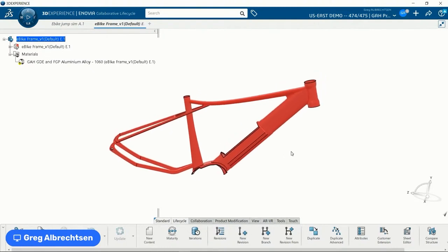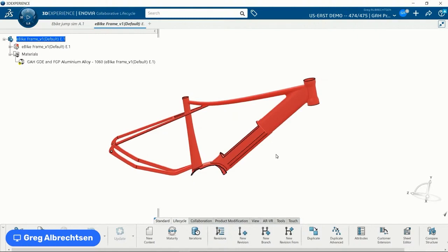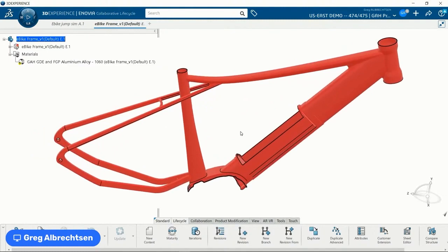Okay, so I'm going to probably be talking pretty fast. I got a lot to show, but again, ask me some questions as we go along here. What we want to do is prepare this frame for an impact study. If you refer back to my helmet presentation, I did some shell meshing, some solid meshing, some TEP meshing. So I did a lot of different meshing, but those different meshes were on different parts. So even though we were doing some mixed meshing, those were on different parts. And as I look at this frame here, it's a thin tube frame.